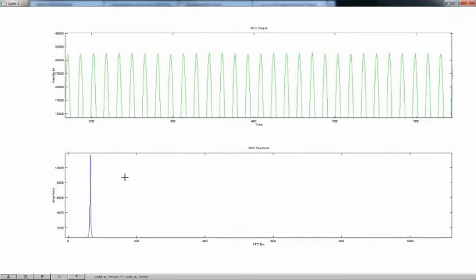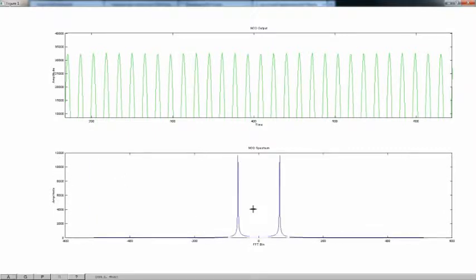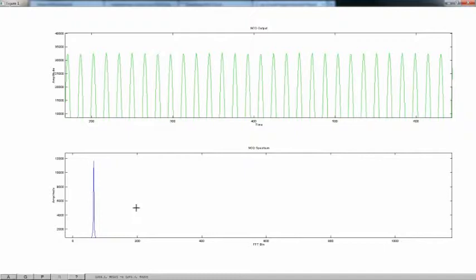So let's go ahead and look at the spectral output. I'm going to go ahead and shift the image frequency, move everything down to 0. So here we see the FFT is reporting that this particular tone is visible in bin 65.